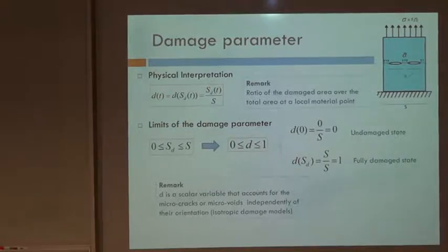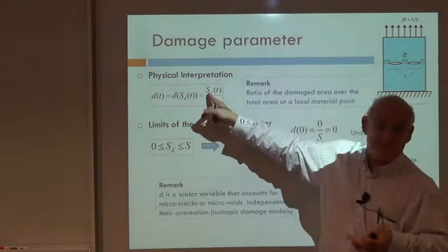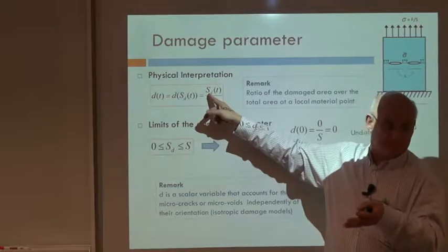And then at a certain point, the material is also able to sustain stresses in an undamaged stage up to a certain point. Beyond a certain point, due to certain microscopic perturbations, whatever it is in there, this damage starts appearing, and the value SD, which initially is 0, starts evolving.